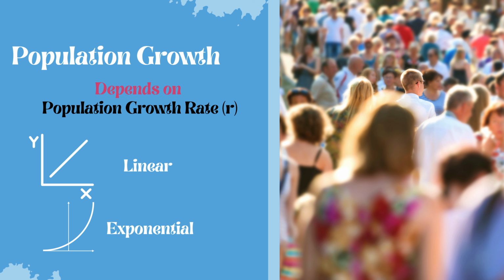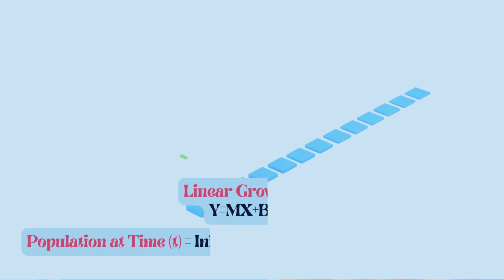So why does this pattern matter? Knowing the pattern helps us predict how much the population will grow in the future, say 20 or 30 years. Linear growth is typical in stable communities. Exponential growth might occur in cities with high birth rate or immigration. Remember, accurate population predictions are essential for designing water supply systems that can meet everyone's needs for years to come.